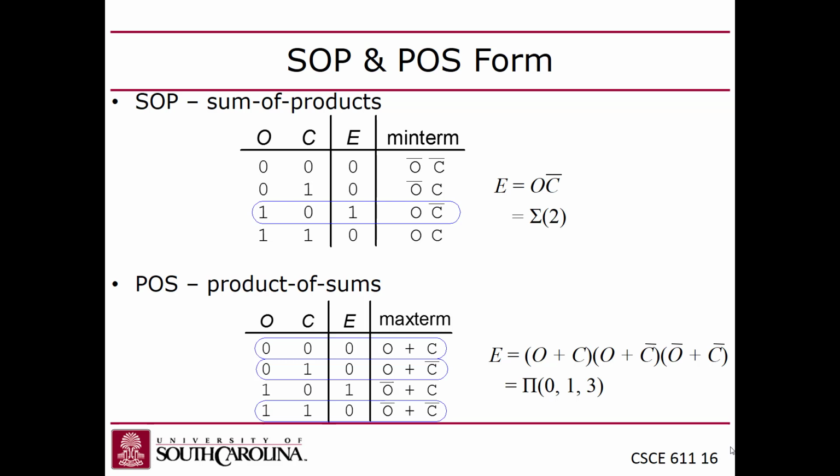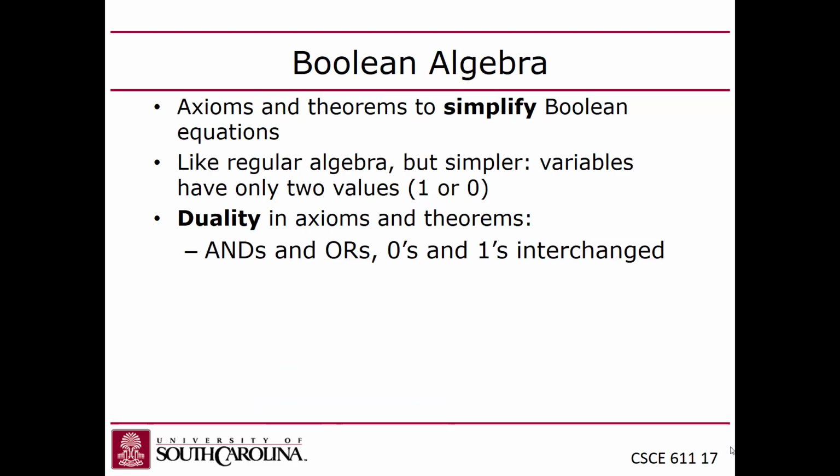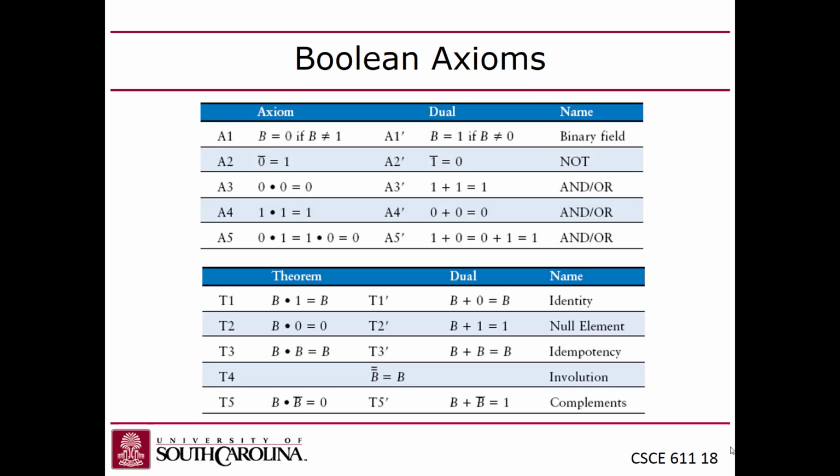Okay. All right. And this is also the reason why you would want to simplify a Boolean logic behavior before you implement it in hardware, because you'd be using less resources, right? So, you can do that with the Karnaugh map as I did over there earlier, or you can do it algebraically using Boolean axioms and theorems. What's the difference between an axiom and a theorem?